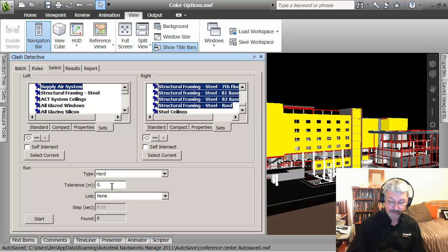The values set here for tolerances would be just common sense or trial and error, but if you set the tolerance to say 0.001 meters, then even if the object were within 0.001 meters, it's not going to show a clash. It has to be a bit more pronounced before it's going to report on the clashes, and it ignores anything within that distance.